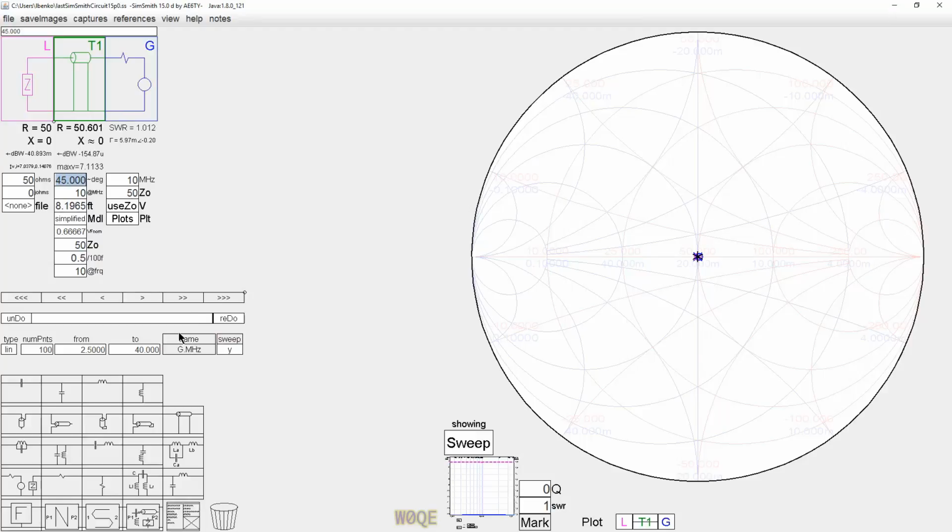I've picked up a lot of Teflon coax over the years, and some of the stuff has been like 12, 15 ohm coax made by people like Microdot, and it's kind of useful for some functions, particularly transmission line transformers for solid state amps and stuff like that. May not be very useful for antennas, but nevertheless, let's look at what we got. Let's suppose we were given a roll of coax, and I'm just making this up now.